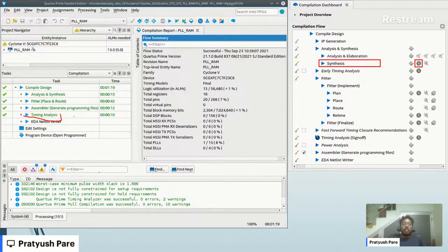As a designer, you need to know what time it takes, what the setup margins are, and what the hold margins are for your design. We can have some other session on setup and hold also. But currently, timing analysis is very important for a designer, either in FPGA or in ASIC. In ASIC, it is very important. In FPGA, we can wave it off through some SDCs. We can reduce the clock frequency. It's just for testing purposes, so not a matter of fact.